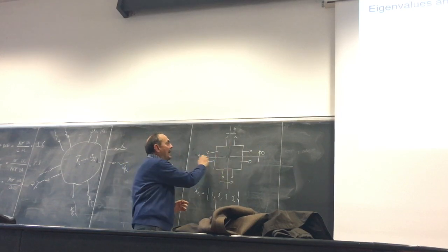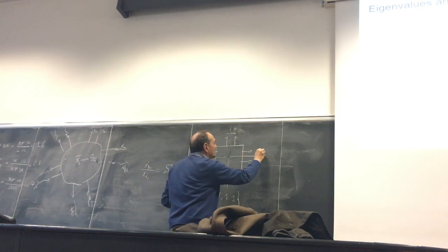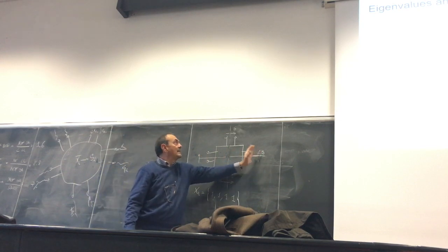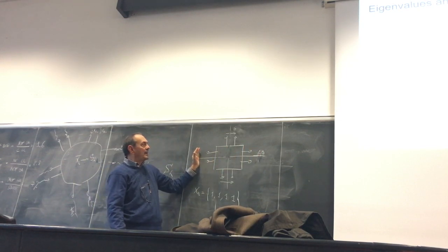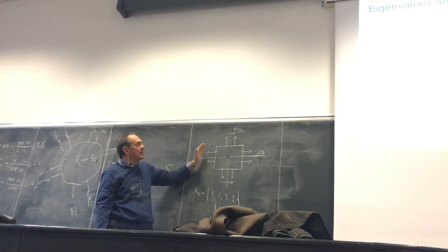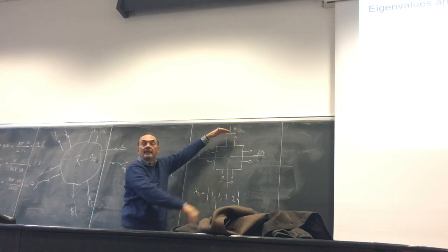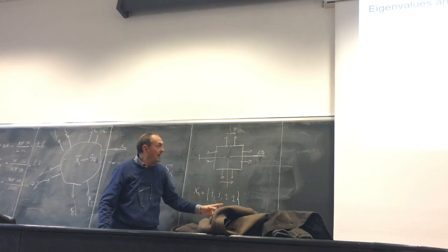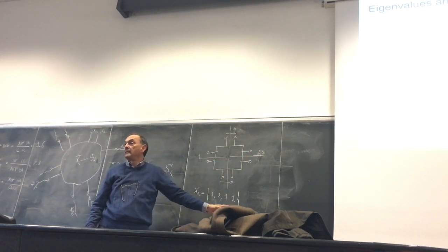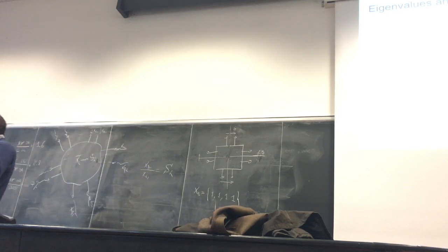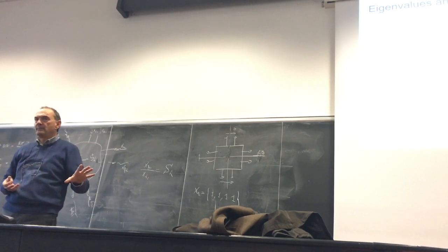So here I could have 1 and here -1. This is the situation where in the vertical plane I get a short circuit, and in the horizontal plane I get again an open circuit. And so in this case, this port will have -1 instead of 1. And so on. There are 4 combinations, and each combination defines an eigenvector.